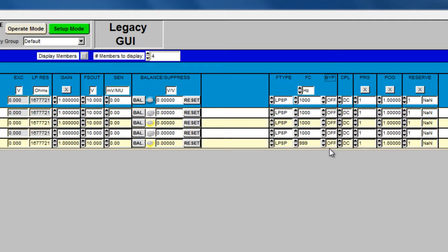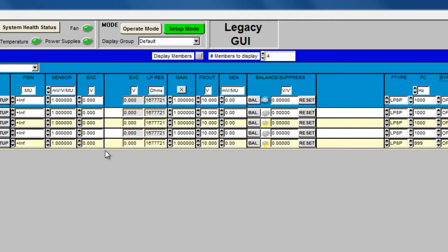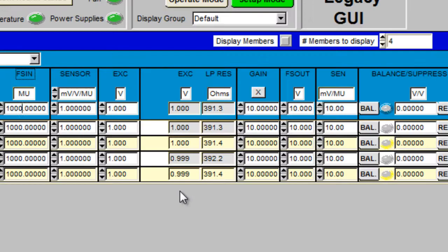For specific card models, the 28000 GUI offers real-time sensor health and excitation monitoring capability. This feature utilizes onboard capabilities on the signal conditioning cards that make real-time measurement of the signal conditioner and sensor operating parameters and report these back to the GUI software. This monitoring capability measures the loop resistance of the sensor and cabling as well as excitation levels delivered to the sensor. This capability allows for the integrity of the sensor, cabling, and excitation supply to be monitored during test.